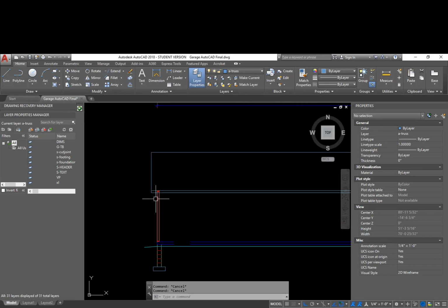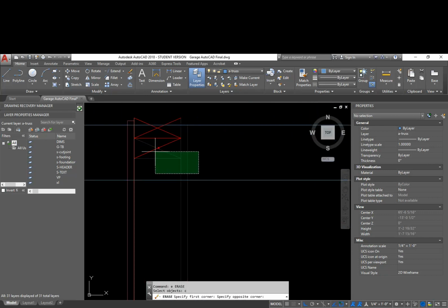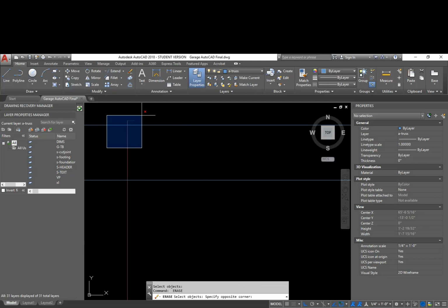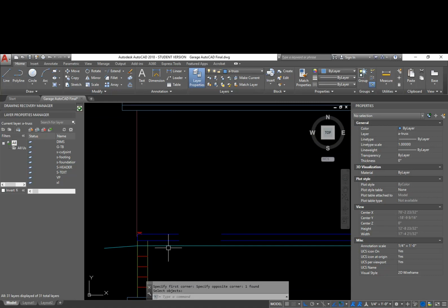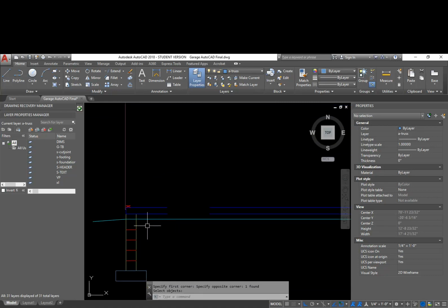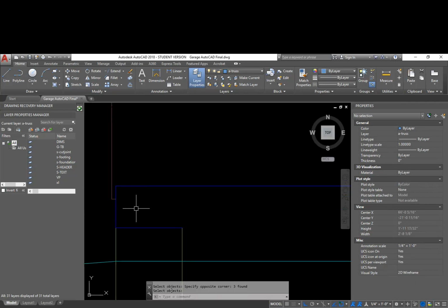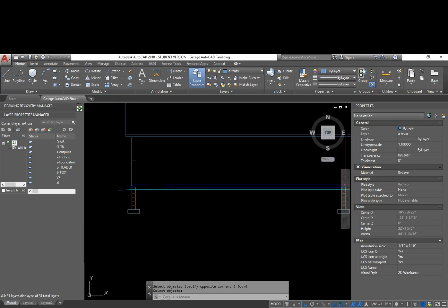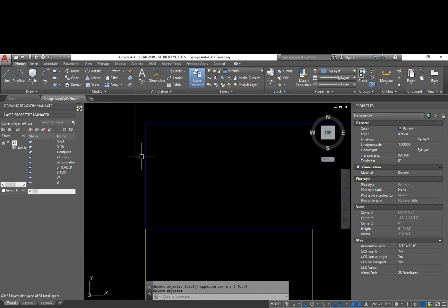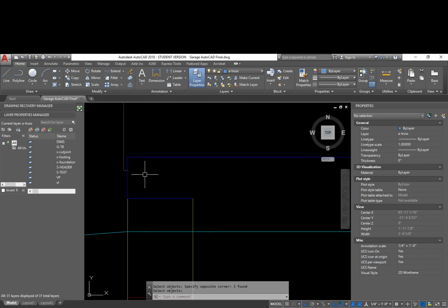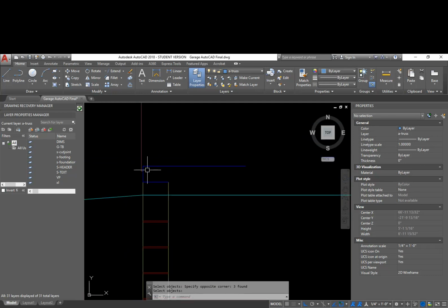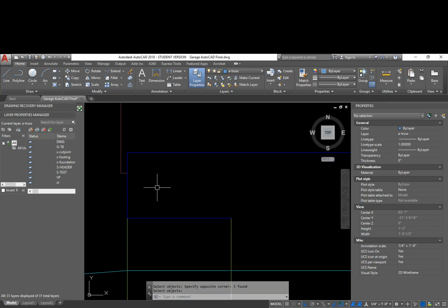And I'm starting to get more and more of an elevation here. I'm going to erase all these things. I'm going to see parging from here to grade, so I can get rid of that line. Get rid of that. My siding is going to extend down to this point where my OSB covers, so it's going to extend past the slab a little bit. We were doing that so that we created that natural drip edge.